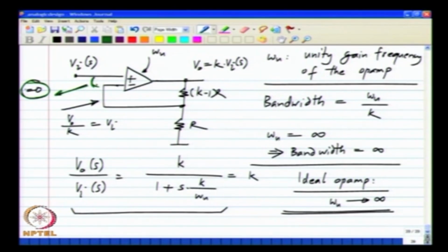Okay. So, using that you will be able to analyze any ideal op amp circuit, and this is a good first step. So, let us say you see an op amp circuit that you have never seen before and you think that it is an op amp circuit that uses negative feedback, then you can assume that the op amps are ideal, meaning the input terminals of the op amp are at the same voltage, that is the error in the negative feedback system is 0, and go ahead and analyze it. After that you can put in all the details to the circuit and then analyze the circuit.